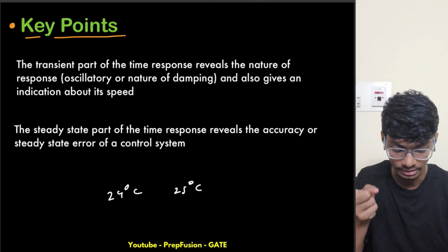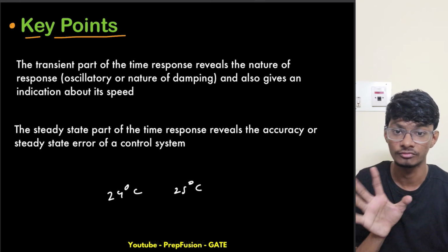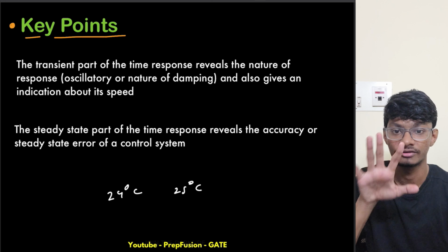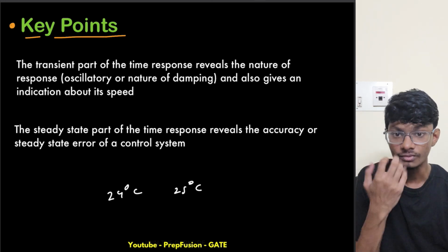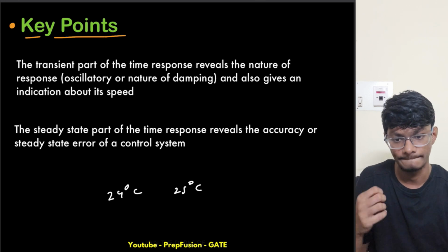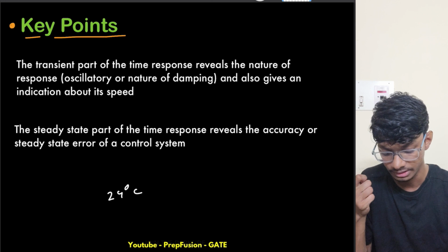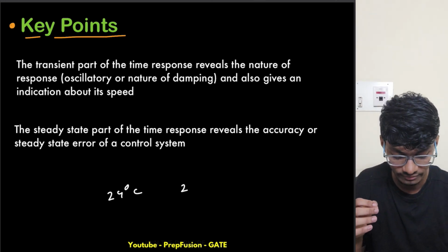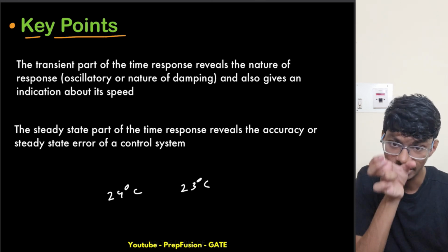Now again it will give the controller signal that it is still 25 degrees centigrade and we have to further cool the room, so it gives some more cold air. Now for some reason, after giving more cold air, the temperature directly reduced from 25 to 23 degrees centigrade. Obviously it won't go perfectly to 24, it will go slightly below 24.